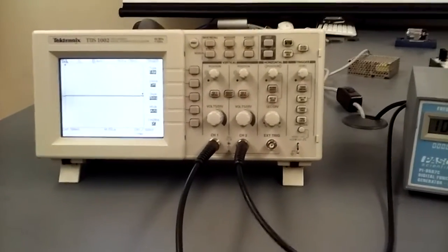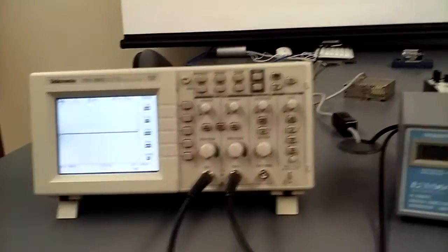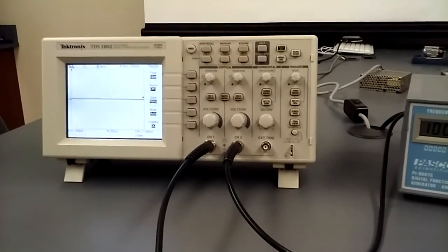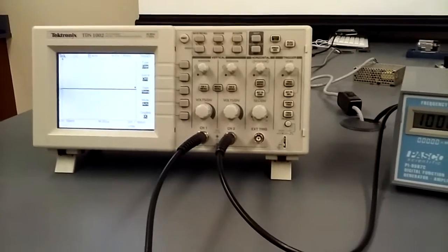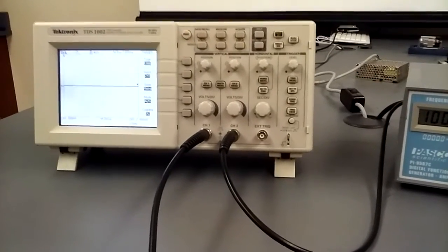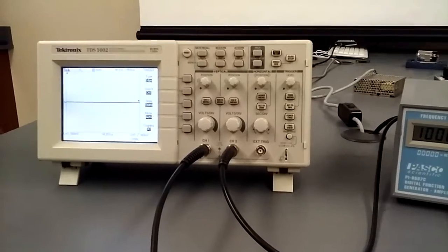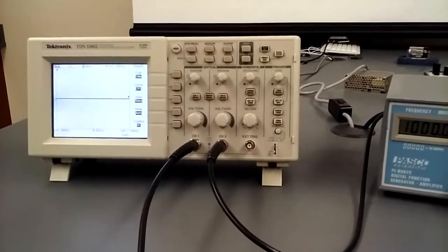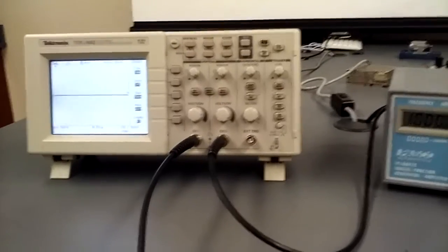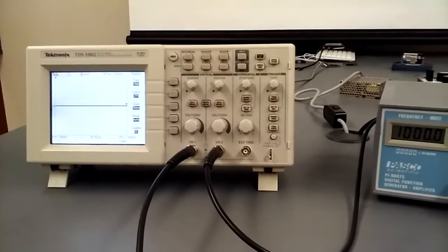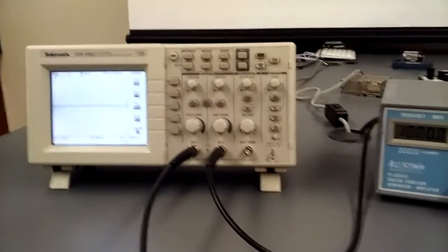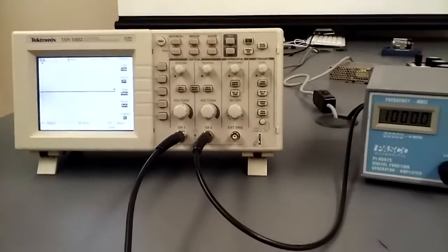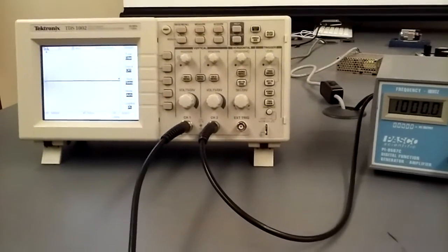So here's the oscilloscope. So what does an oscilloscope do? Well, it's basically like a voltmeter. You measure voltage and it connects like a voltmeter. You go parallel to whatever you want to know the voltage of, okay? So outside your main loop of circuit. But instead of just giving you one numerical value like a voltmeter or a multimeter does, it's going to show you a picture. It's going to show you a plot of voltage as a function of time, okay?